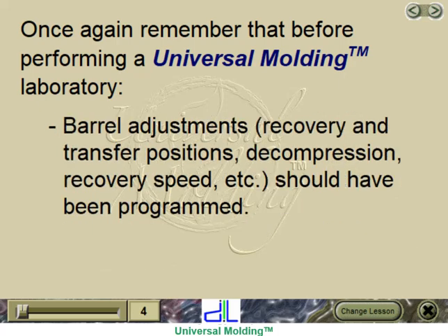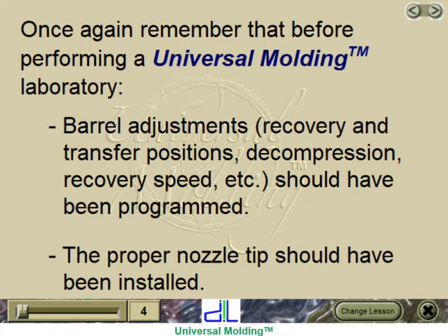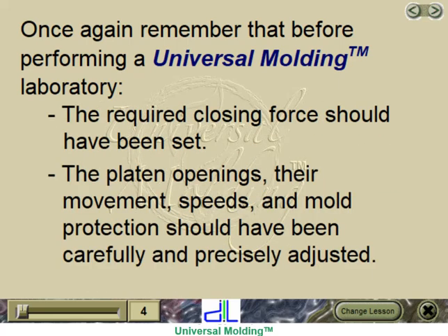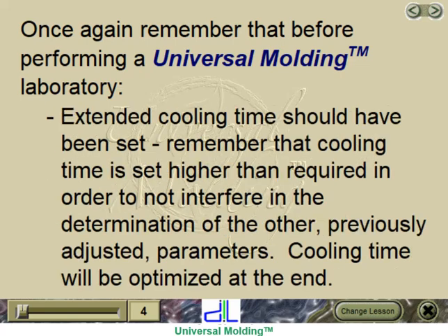Barrel adjustments, recovery and transfer positions, decompression, recovery speed, etc., should have been programmed. The proper nozzle tip should have been installed. The required closing force should have been set. The platen openings, their movement, speeds, and mold protection should have been carefully and precisely adjusted. Extended cooling time should have been set.